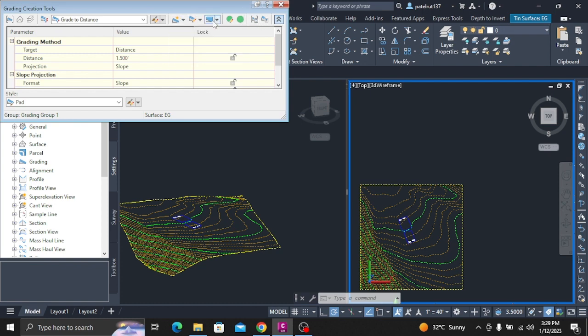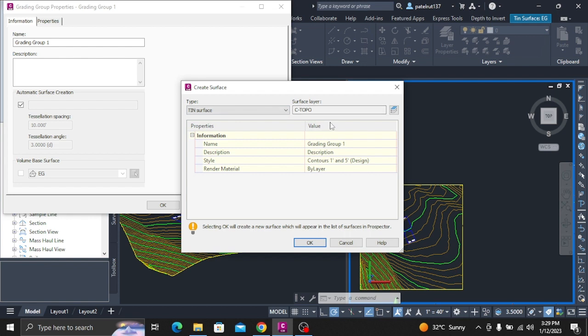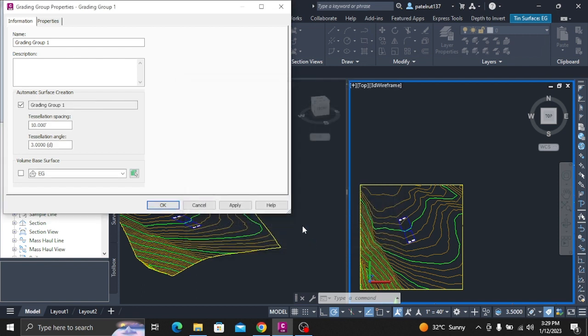Click OK. In the Assign Elevations dialog box, select from Surface. Make sure that the Insert Intermediate Grade Breakpoints checkbox is selected and that Relative Elevation to Surface is cleared. Click OK. Note: for more information about using the Relative Elevation to Surface option to make a feature line relative to a surface, see about Relative Feature Lines.